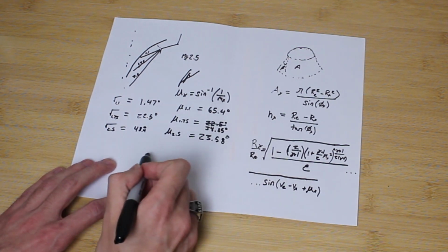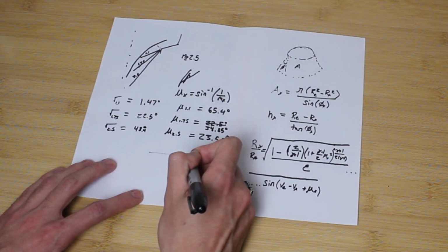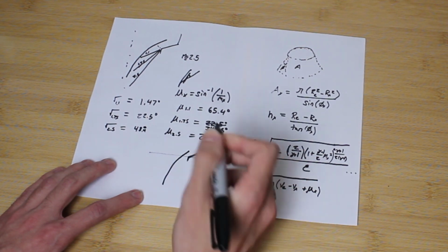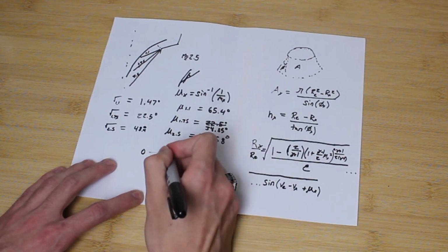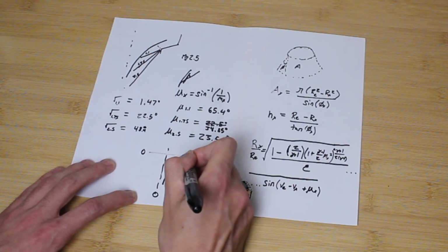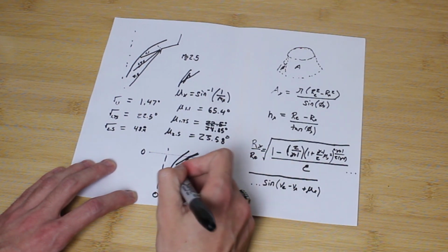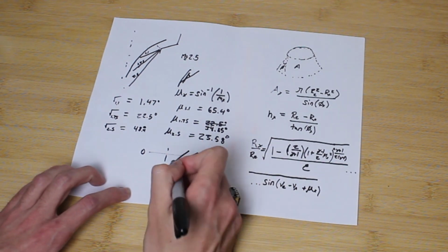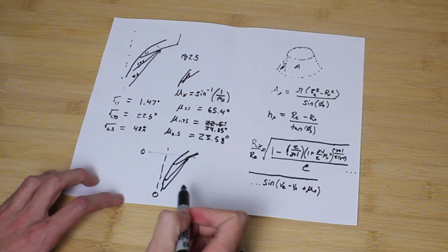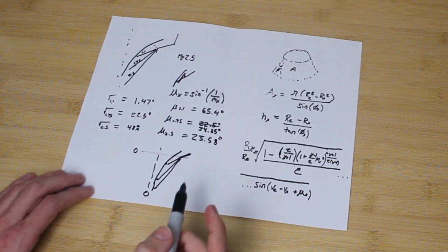And this has given us a set of 3 points, so just to finish off. We've got our shroud here, and we've got our spike geometry here, where this is 0, and then this center line here is also 0, and we have 3 points for Mach 1.1, 1.75, and 2.5. We have these positions now in 2D space, and then to derive our 3D nozzle geometry, all you have to do is rotate it. Let me just go ahead and get those all set up.